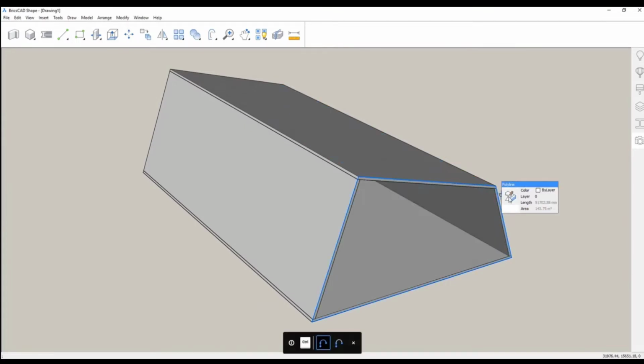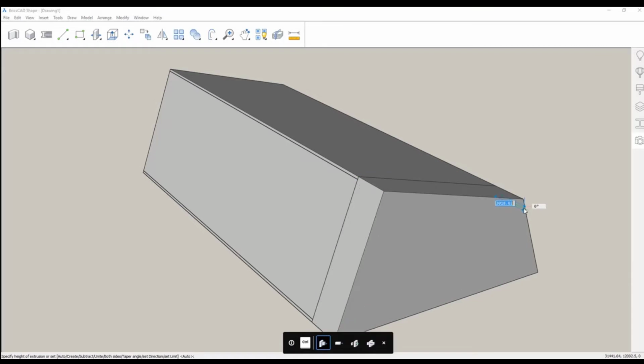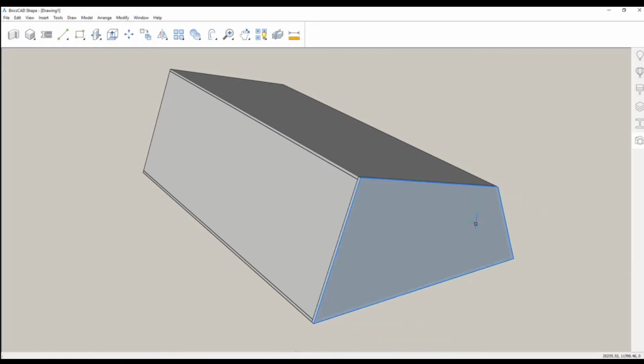Done. Now, next step will be to create the end caps, or the 2 outside walls of our building space. Quickly drop those in. And now let's use simple 2D geometry to drive a cutout in the front of the building. This will be the entryway.